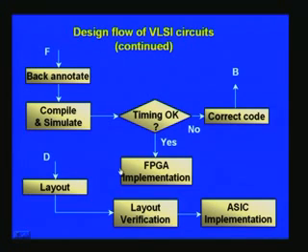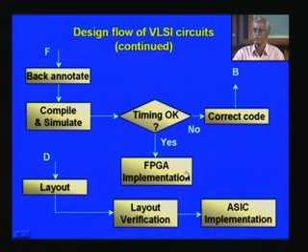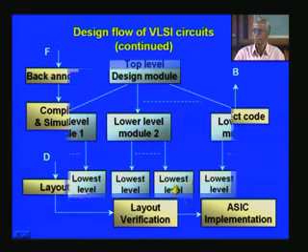So if you had coded using vendor specific tools, then naturally you can't use it in the ASIC flow. So my approach, what you have already seen here, is friendly for the FPGA platform as well as the ASIC platform, so long as you stick to that style of coding. So it is, so to say, a universal way. So we'll try to stick to that particular thing. As far as possible, avoid vendor specific standard modules, I mean their own modules.